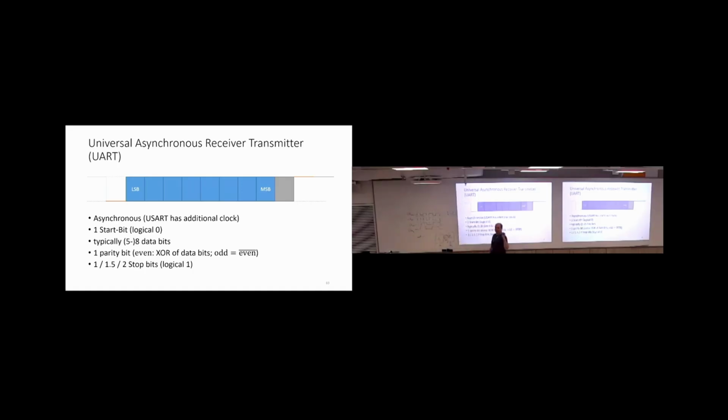Probably you remember Nyquist criterion? So if you want to reconstruct a signal, you have to sample at least with a double rate? No? Okay. So effectively, if you want to reconstruct a signal, I think you have at some point some signal processing stuff, and this definitely comes. If you want to reconstruct a signal, you need to sample at least with twice the frequency.